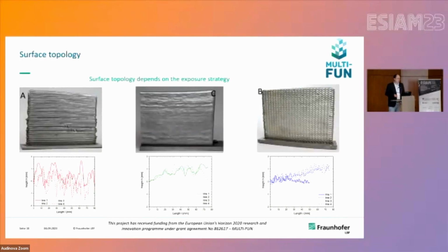but I think more important than the anisotropy is to describe the influence of this structure in a good way. Here you see 3 different walls which are built with different exposure parameters. We have a really rough one. I'm not sure if it's just roughness or more or less a topology. Then a better one with a nice pattern, and also one that is more or less smooth.